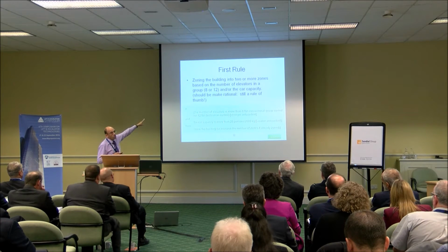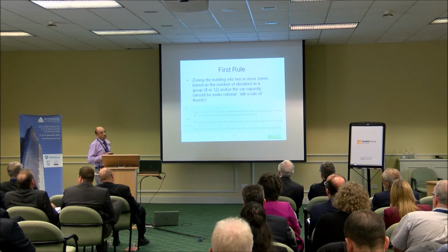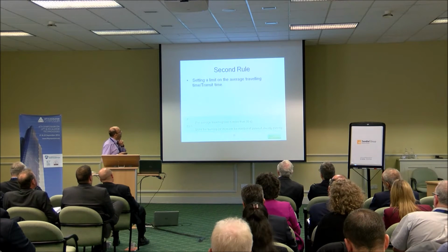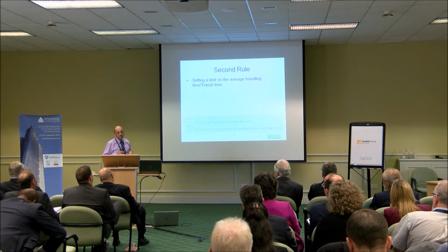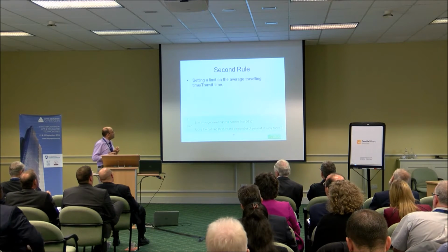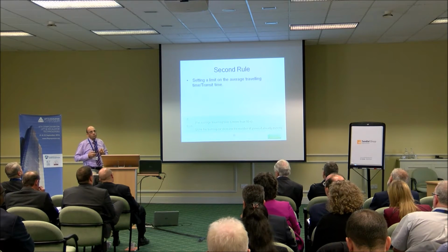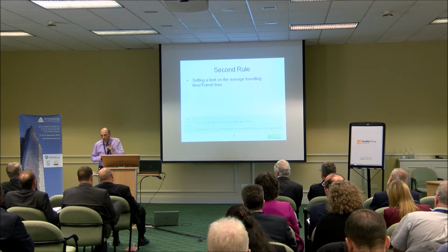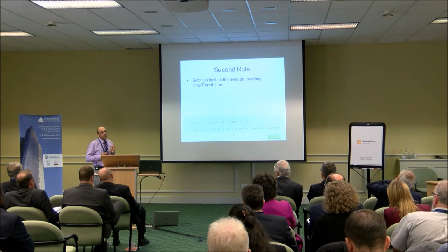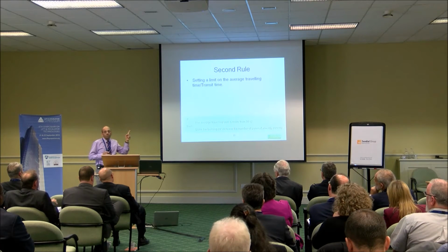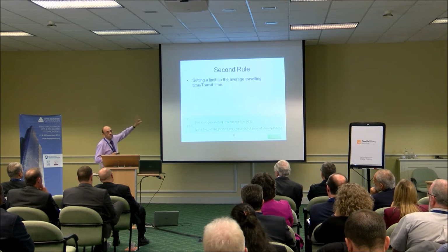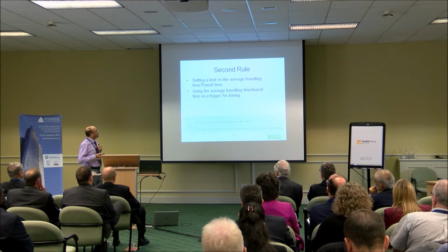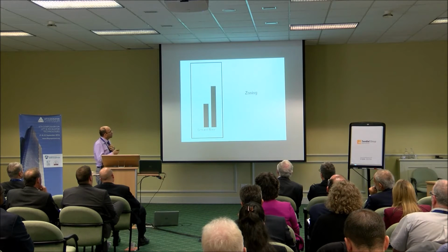So really that's still a rule of thumb, but at least that's the start. The second one is about zoning. If the traveling or transit time, as the correct expression is, exceeds a certain limit, usually you need to zone. That's a trigger for zoning, rather than saying, if you have more than 20 floors, you zone. That's the rule of thumb. This is the rational rule. It says what the reasoning behind it is.